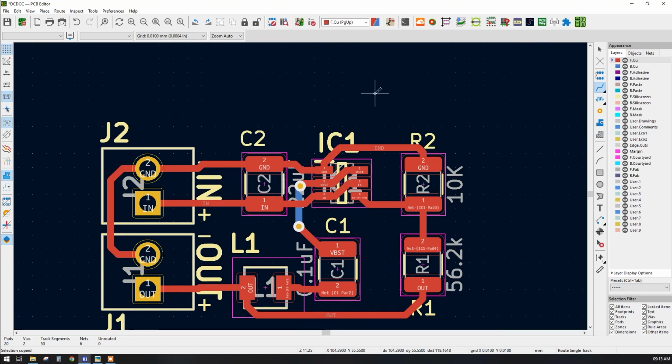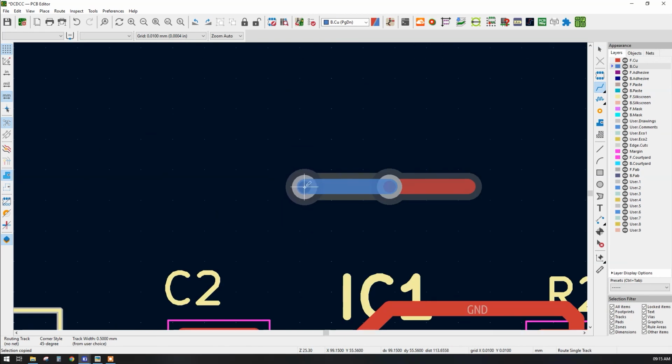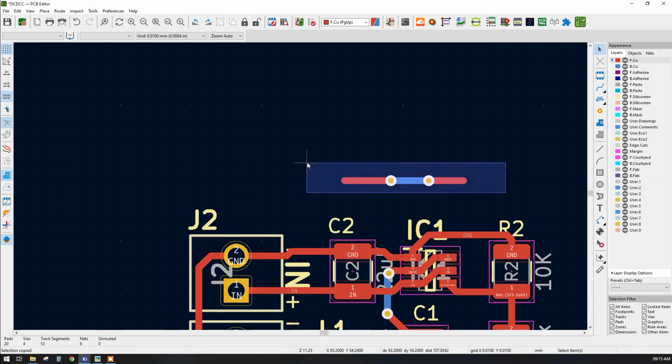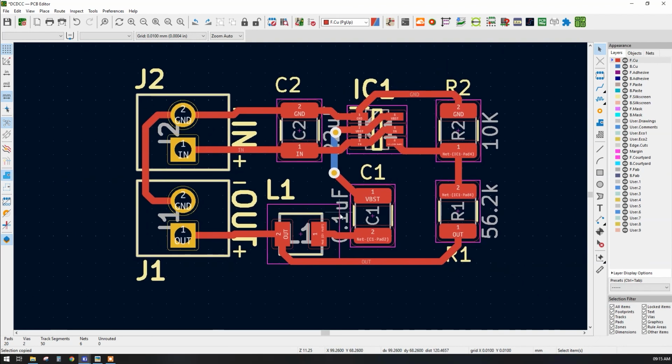For example, again if you want to practice, then click on the wire, press V, it will select the via. Click, and it will put the via on the PCB. Again press V, it will select the via, and click on the PCB, so it will put the via on the PCB and it will change the layer. Okay, so this is how you can use the track and via in the different layers. Okay, so this is our routing.